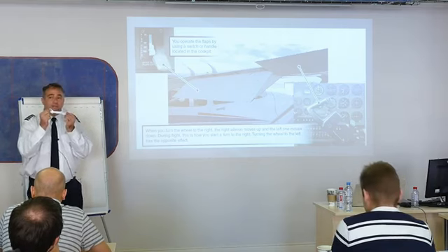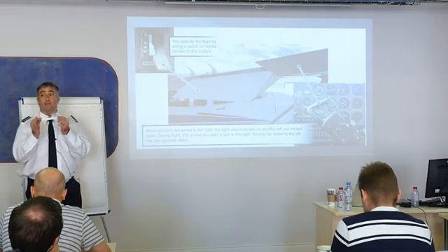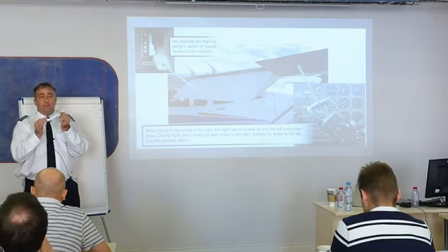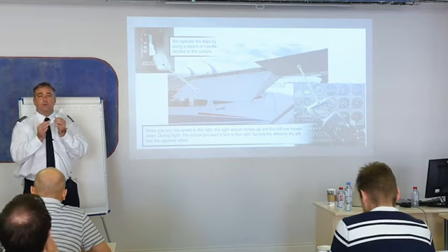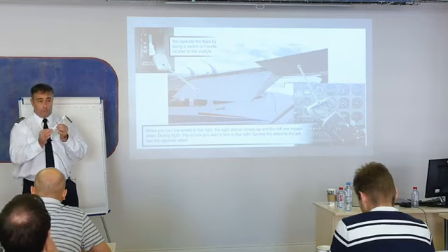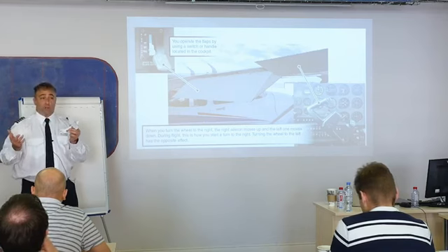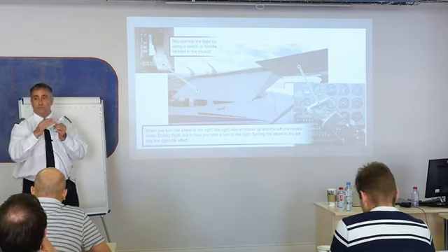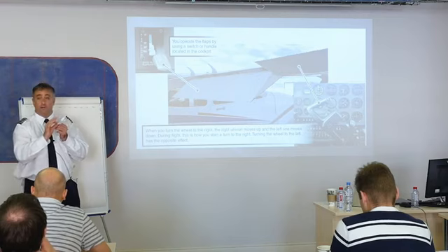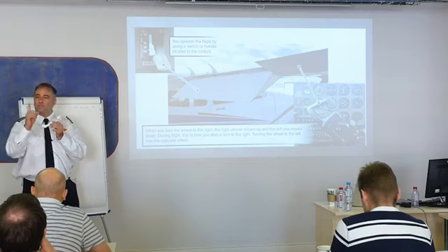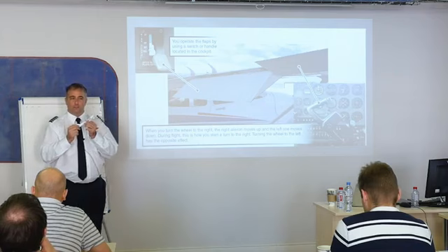Depending on how fast I'm flying this airplane in level flight, I may be very close to no longer being able to support the airplane in the air. There's a condition called a stall, where the airflow separates from the top of the wing, and I no longer produce enough lift to keep it flying.